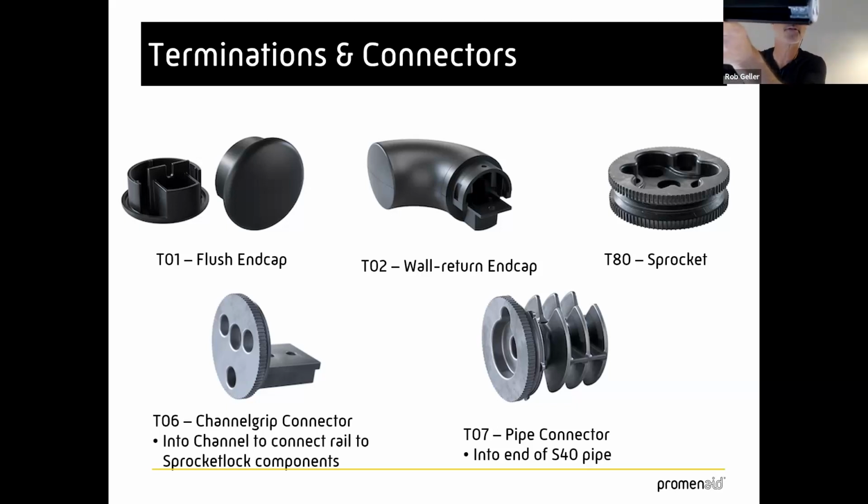Let me see if you can see that. This goes on with a set screw. This is a connector. They undo the set screw, pop that on. This is a connector. This is how a bend connects to the railing, just with this sprocket. But it just goes on with set screws, and they have a code compliant railing within seconds.